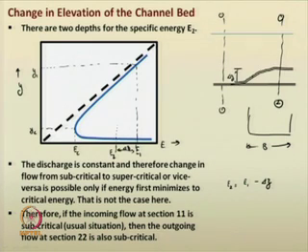From this, you will see that there are two depths for the same specific energy E2, one supercritical depth and one subcritical depth. You have to appropriately select which is the depth of flow.